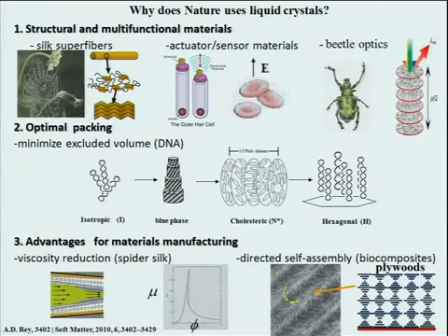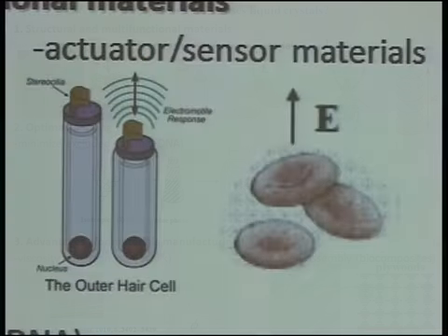And this type of membrane is known as a flexoelectric membrane. So flexoelectricity tells you that the electric field couples with curvature. There is an intrinsic difference between flexoelectric and piezoelectric. Piezoelectric is where the electric field couples with the area, with the dilation. In this effect, the electric field couples with the curvature.